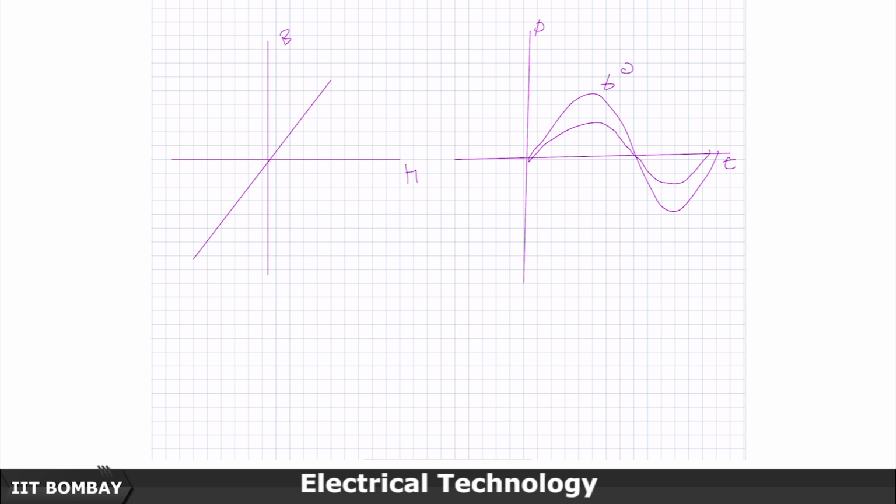So, therefore, this phi would have become sinusoidal, and I also would have become a sinusoidal current. For phi and I, in that case, if the flux is designed by a sinusoid, the magnetizing current is also going to be sinusoid in phase with the phi, 0 crossings exactly match, rising,